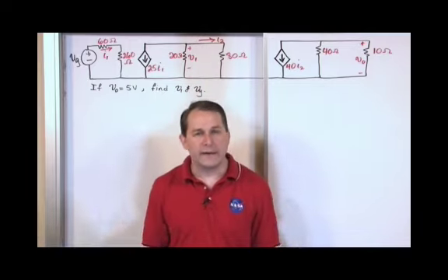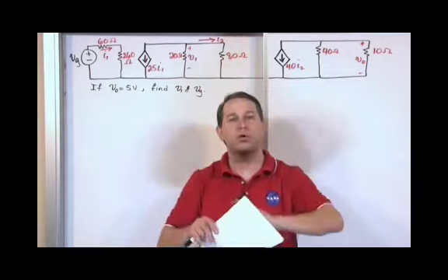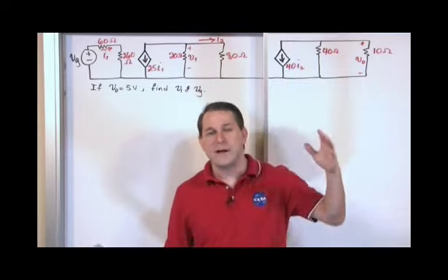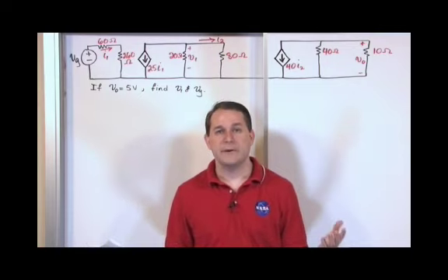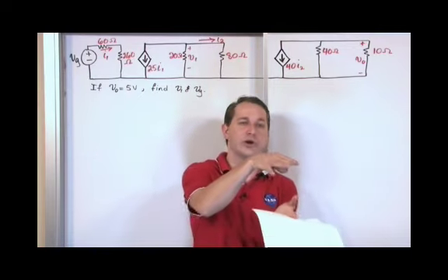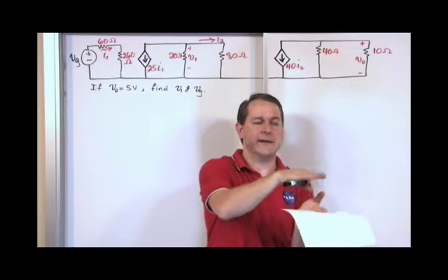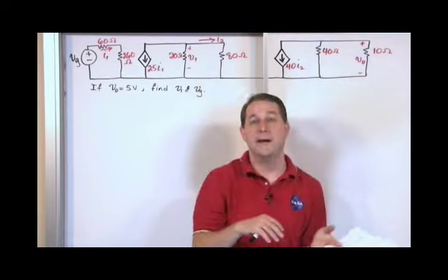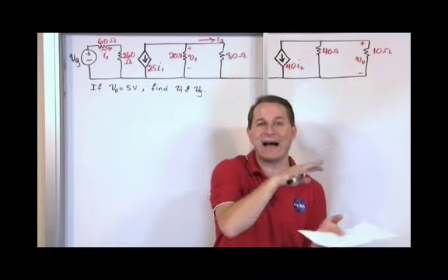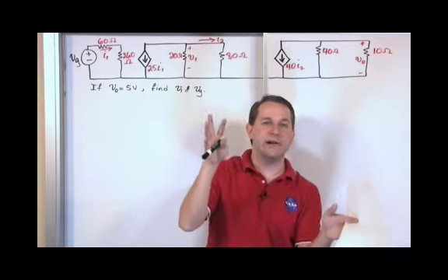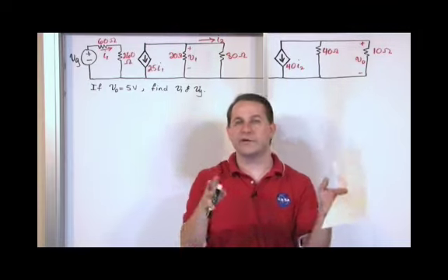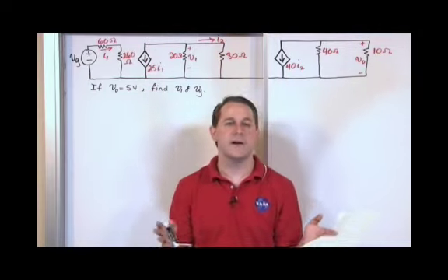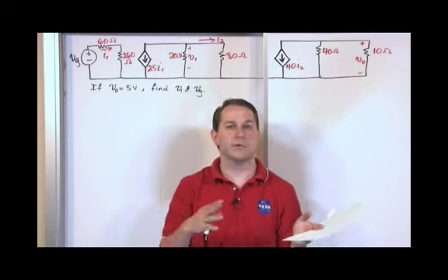If you don't do that, I'm getting a little ahead of myself, but if you don't have a common voltage reference, right, and you just let everything float around, then you get really big problems, because you might have one circuit over here that its low voltage level may not be 0 volts. Its low voltage level may be something else, and it's floating around. It's not tied to anything. So you can get these dangerous voltage changes between different circuit elements if they're not tied down to a common point. It can actually cause arcing and melting and things like that.